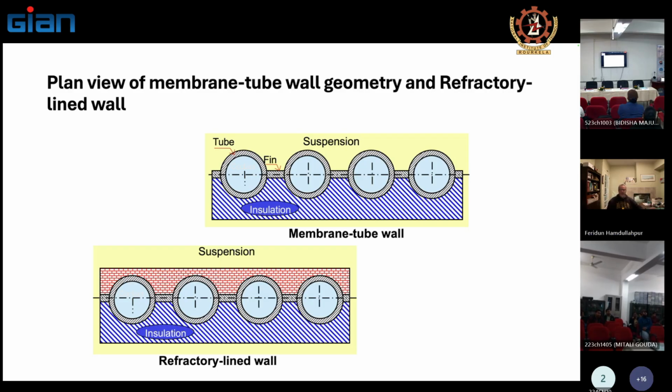So can you imagine every second, hundreds, thousands of these bombarding these surfaces? What will happen? After a while, these surfaces will get weakened. It will eat up the wall thickness, and after a while, your heat transfer tubes will fail, and the working medium, whatever, water, steam, starts escaping. And imagine this is a 160 megawatt electric boiler, and then you'll have to shut it down, and it will take months and months to repair.